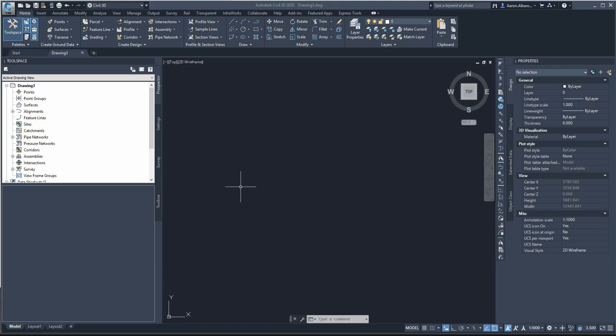Where our focus, if you remember, during the rural road design was on the balance between cut and fill, the K values, the radiuses for the horizontal alignment turns, and the K value for the vertical profile. We've got slightly different things that we have to consider and focus on during urban subdivision design.